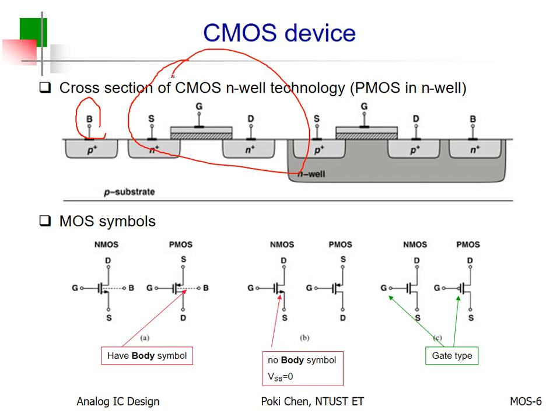And then the other reminder is because the body here is P minus, right? So how can you connect your body to your P substrate? Through the help of P plus. This is a very important idea. Don't say, hey, look, this is NMOS. For source and drain, they are doped as N plus. Why? Because they need to have two parasitic diodes from the very beginning.